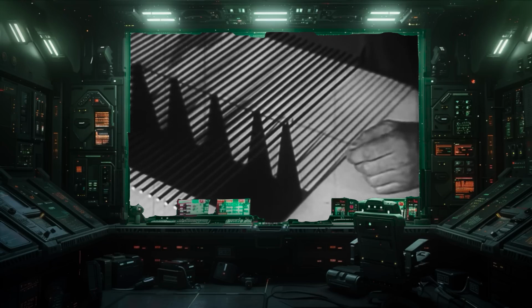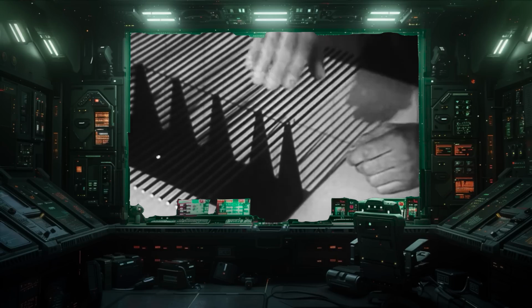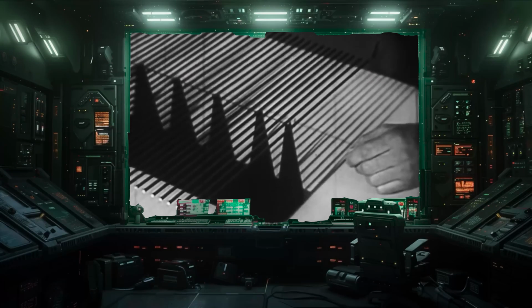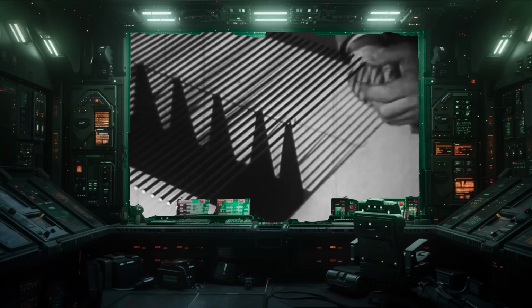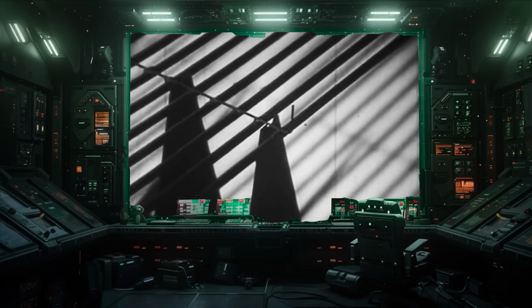The waves which travel on this machine are really waves of twist or torsion, which propagate along this central wire. Attached to the central wire are these cross arms, which translate the torsional motion of the central wire to the up and down transverse motion of the ends of the cross arms, which you see. The entire structure is supported in a set of bearings which permit the central wire to twist freely.